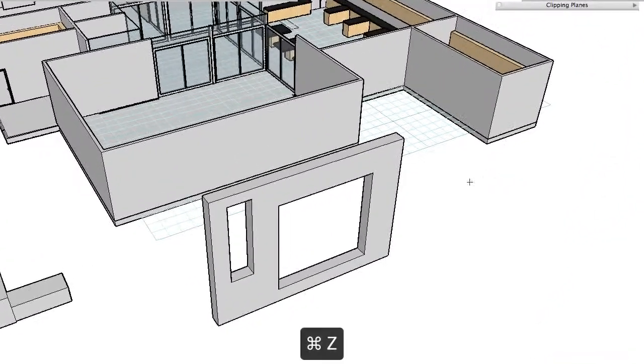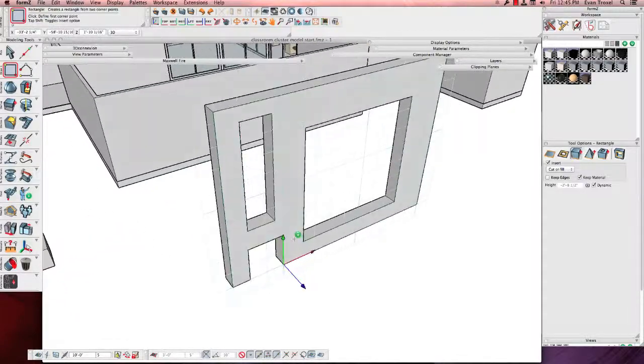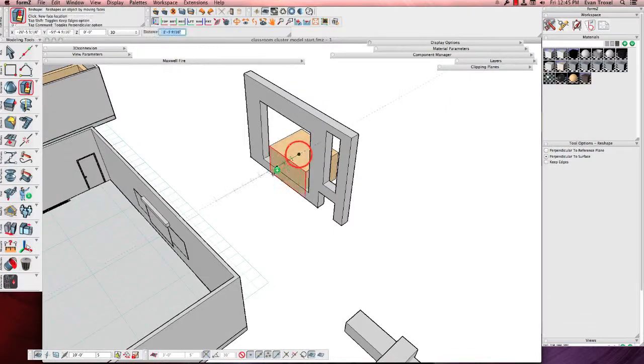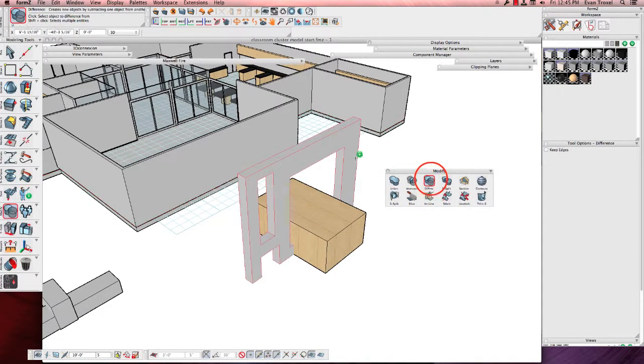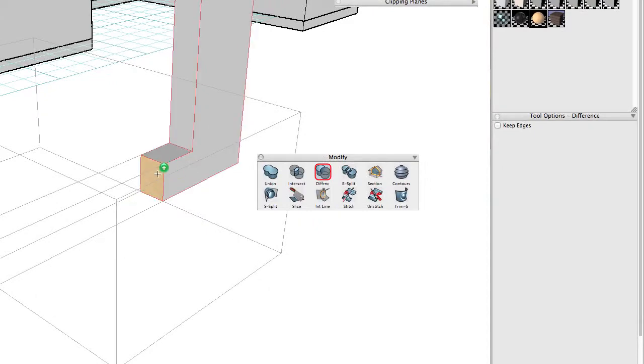But what the question, I think, was regarding was if I go here and say draw with my wood material and do a cut. Let's see what happens here if this works. Nope, it didn't. It didn't leave that material. Sometimes what happened in the old version of FormZ was when you slice through, and I'm sure it still does this, if I maybe draw a separate object out here and let's just pull that through there and then do an actual Boolean difference. So I'm going to keep the wall, click on that. Yeah, see how it painted those surfaces with a different material.